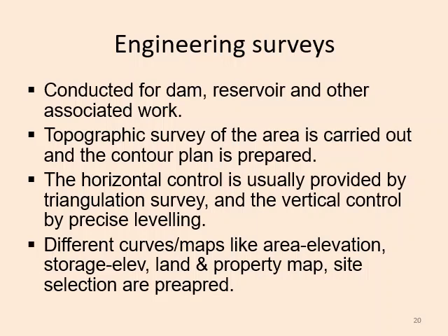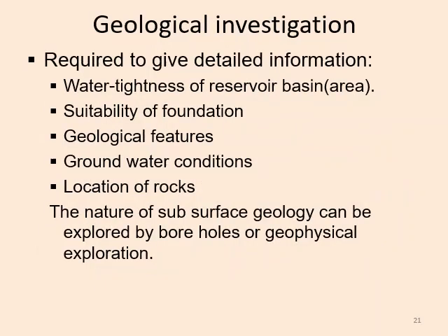The horizontal control is usually provided by triangulation survey and the vertical control by precise leveling. Different curves and maps like area to elevation, storage to elevation, land map, property map, site selection map, etc. are prepared.